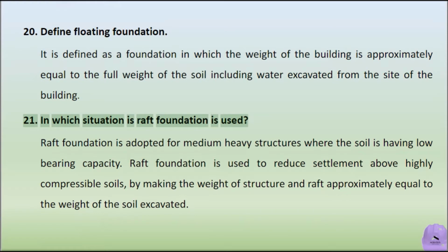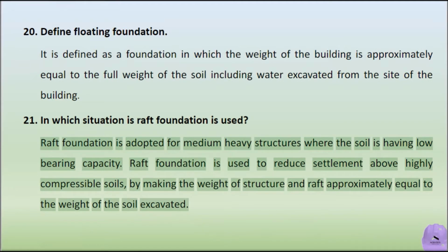In which situation is raft foundation used? Raft foundation is adopted for medium-heavy structures where the soil has low bearing capacity. Raft foundation is used to reduce settlement above highly compressible soils, by making the weight of structure and raft approximately equal to the weight of the soil excavated.